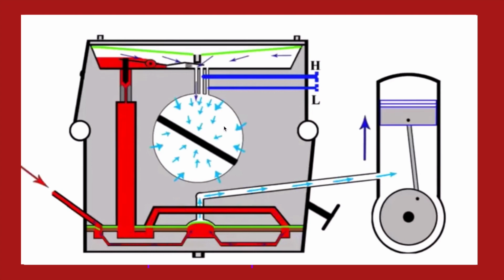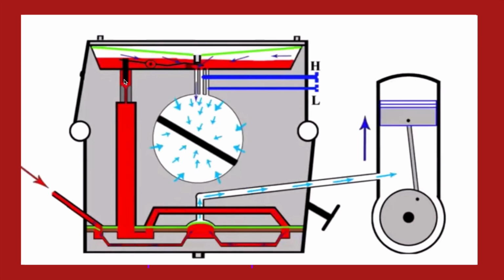On the upstroke, air is sucked into the engine, creating a negative pressure zone near the throat, which causes this diaphragm to be sucked inwards. This diaphragm pushes down on a lever, opening up the needle valve. Once fuel flows into the metering chamber, fuel can then be pulled into the throat and into the engine.